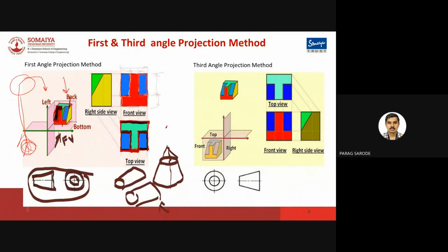Okay. Now, what about the side view? The position of the figure is such that we will be able to see the right side view, not the other view. But it doesn't mean that we cannot draw it. Generally in engineering drawing for orthography, the view is positioned such that, looking in this direction, which is the prominent side available? This one. Right side. Correct. So that's why we will draw the right side view.